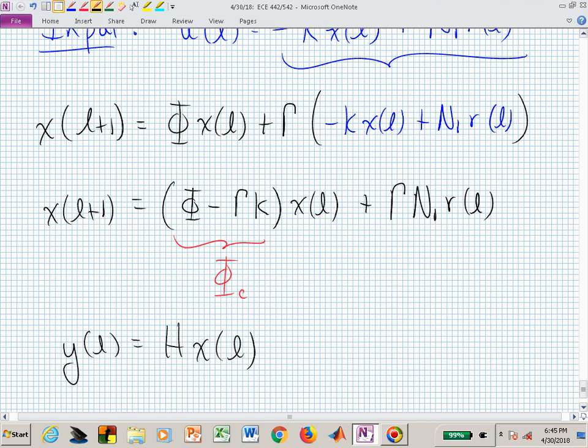So now what I may have to do after class is derive the transfer function between the reference input R and the output Y, and show that if we fix the DC gain to be 1 by the choice of N sub 1, that's a scalar in a 1 input system, then we can make our DC gain equal to 1. And when we tell our system where to go, it will go there if we have a DC gain of 1.